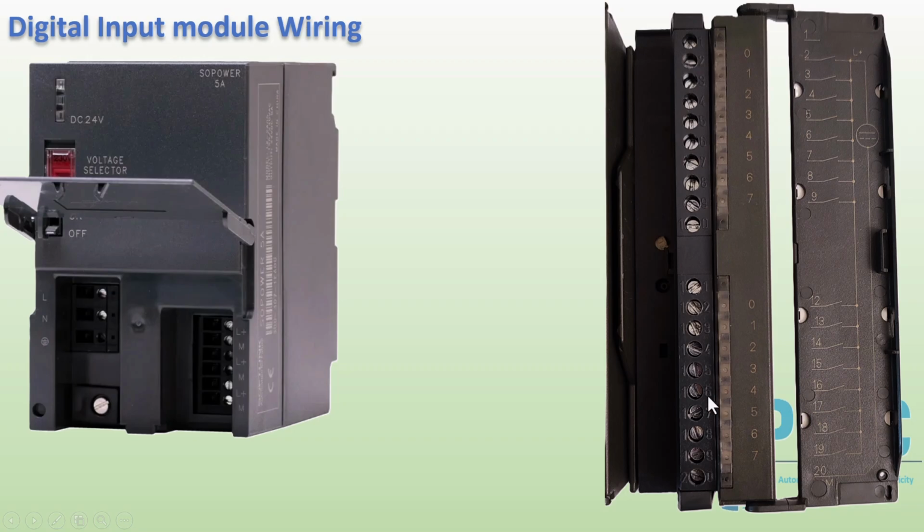The module has 20 terminals in total. Terminal 1 is empty and not used in wiring. Terminal 10 and Terminal 11 are also unused. Terminal 20 must be connected to the -M terminal of the power supply. To properly activate the inputs, follow these steps. 1. Connect the -M terminal of the power supply to Terminal 20.